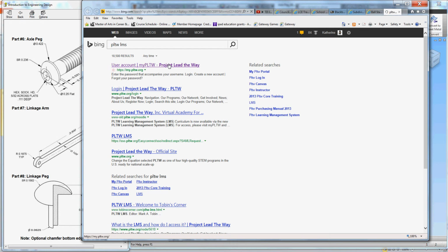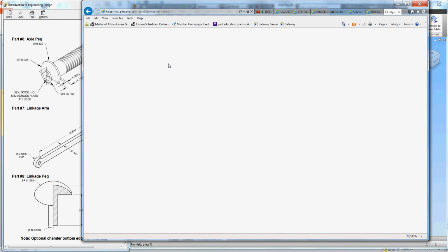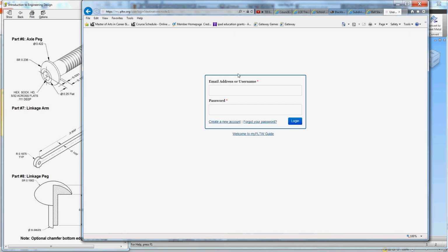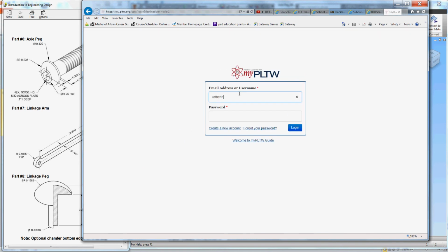Alright, just leave it at 1 inch because the entire shape itself is 1.25. So if you just leave the offset at 1 inch, it'll just go ahead and complete it. Now you want to get rid of the work plane visibility, and you also want to get rid of the work axis visibility. Here you go. You now have an axle peg.